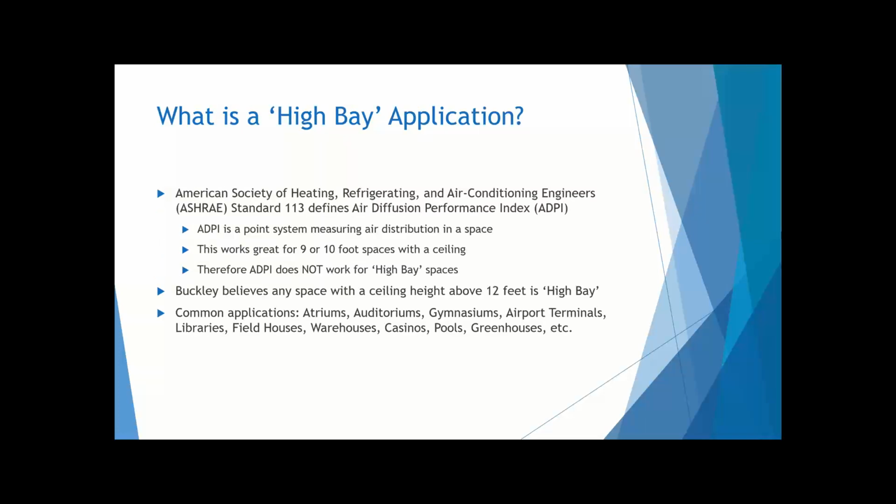So first off, what is a high bay application? ASHRAE Standard 113 does a great job of helping us out with air diffusion in a space with the ADPI, Air Diffusion Performance Index. That's a great point system measurement for air distribution into a space, and it works really well for 9 or 10 foot spaces with the ceiling. However, that means it does not work for high bay applications. So we really need to take what we know about design in those spaces and apply it to a high bay ceiling. At Buckley, we really believe any space above a 12-foot ceiling is considered high bay.